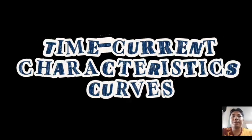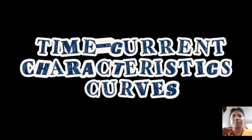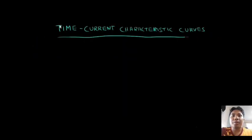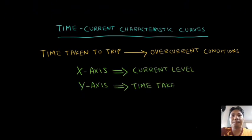In Part 4, we talked about the inverse time characteristic strategy and how we can use it to achieve coordination. In Part 5, we will be discussing the time characteristic curves. Time current characteristic curves are used to show the time taken by the breaker to trip for a range of overcurrent conditions. They define the operating characteristics of a protective device. The x-axis shows the current level and the y-axis is used to show the time taken by the protective device before the tripping action is initiated.